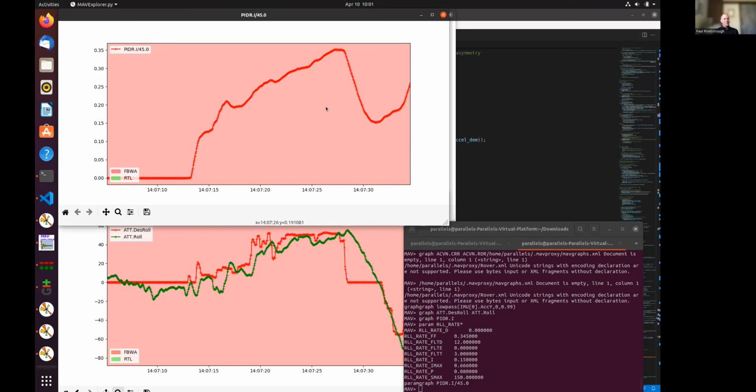So yeah, second log I've seen this happen too. The other log, they didn't lose the aircraft, but it was flying really badly, having a lot of trouble coming out of turns, and then wanted to turn back the other way. And basically the integrator was trying to do the job of what we really should be doing with a side slip controller. We could raise the default integrator so it's a faster speed.